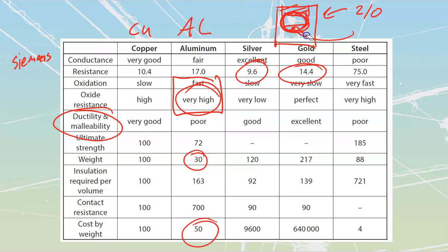So if I take a look at a number 8 conductor placed inside of there, that number 8 conductor will be able to cold flow out to either side to start filling that gap, and it will lose that pressure. We compare that to whatever the minimum size is supposed to be. This thing was sized from 2-aught up to 4-aught. My 2-aught, when I'm going to press it down inside of there, is going to mostly fill it. It's only got a small amount that it can cold flow out. Therefore, it's not going to be able to reduce the pressure all that much off of it.